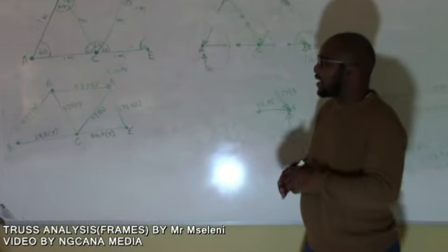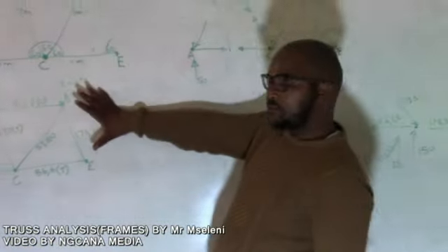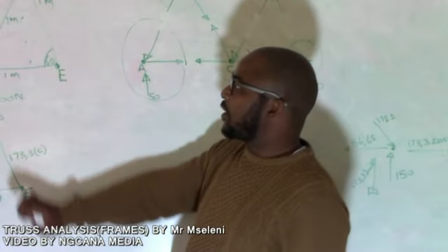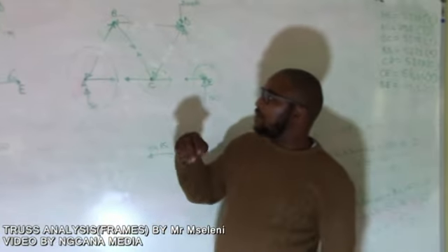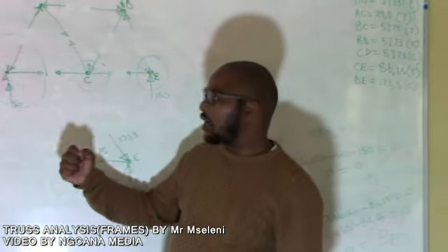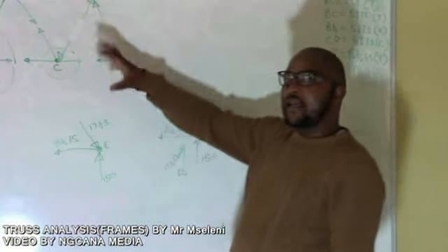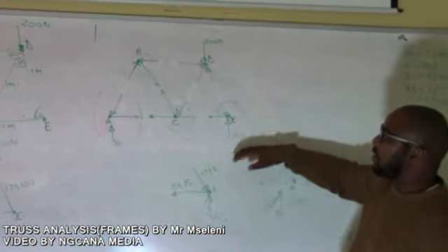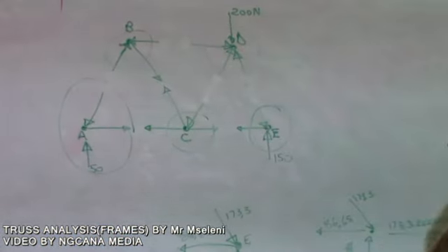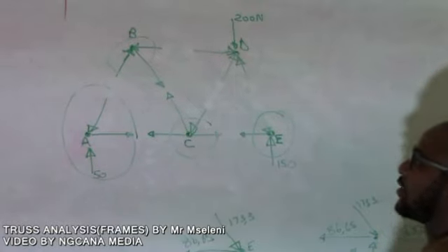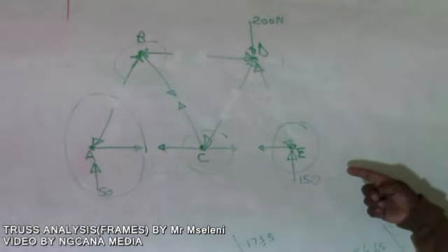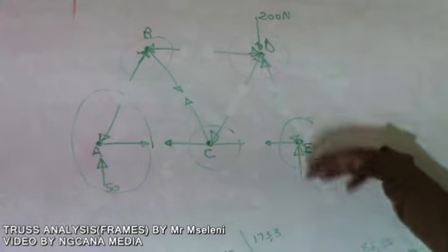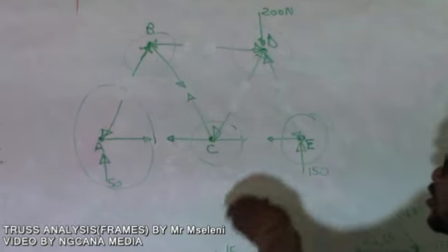And that is the end of the session for this type of frame. It's all you have to keep in mind. The simplest way I found is just breaking your full structure of a frame into its free body diagrams. Once you've got your free body diagrams, it's easy to see the internal forces being applied on each member.